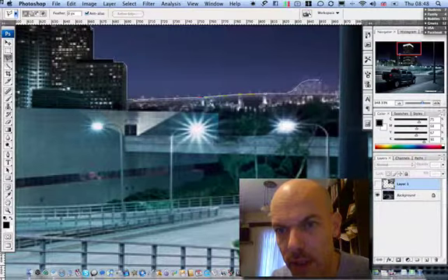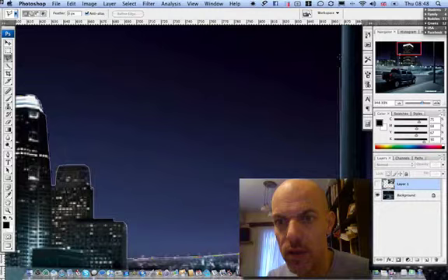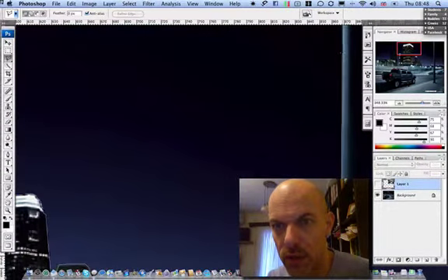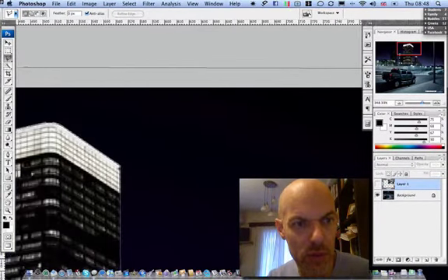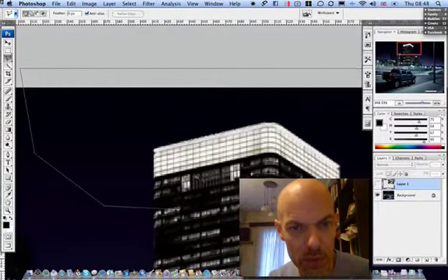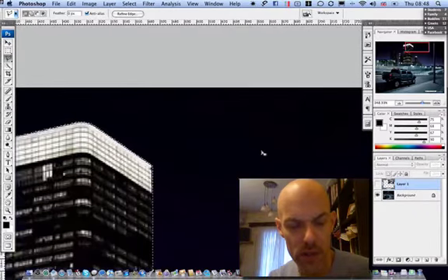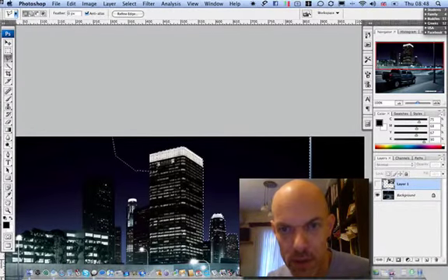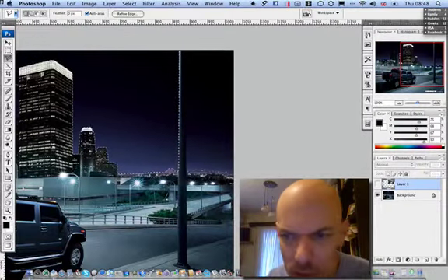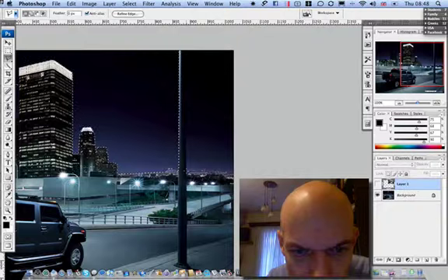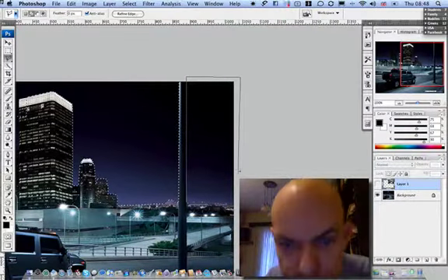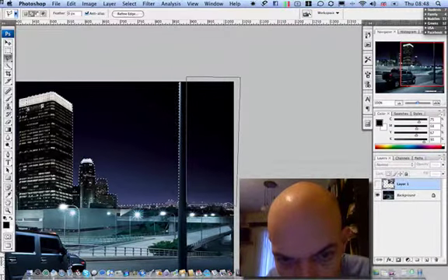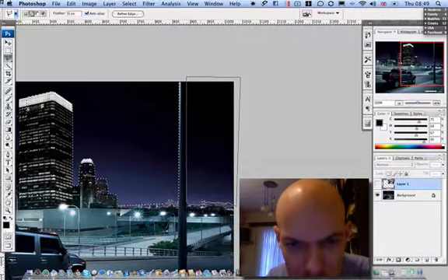So what I've done here now is I've managed to mask off part of the area. And this is this big lamppost that's obviously in the foreground, so it needs to be taken out. I'm going to close this one first. I'm going to zoom out. Notice I've just got to add, by pressing Shift, the rest of the image on there. It doesn't matter how detailed. You see it's all bitty in the background there. It doesn't matter. I just want to get the rough starting point for the mask.